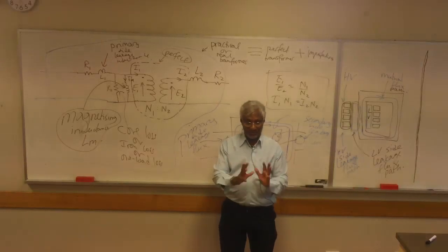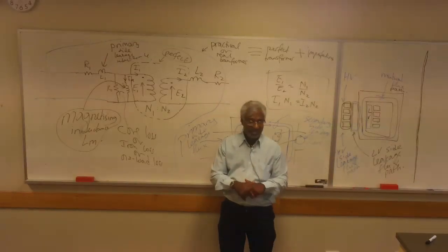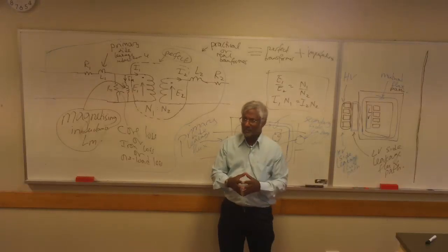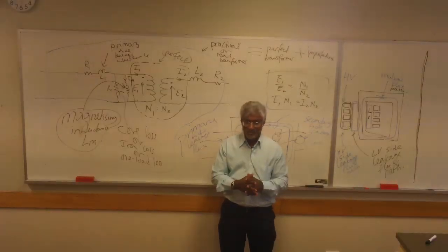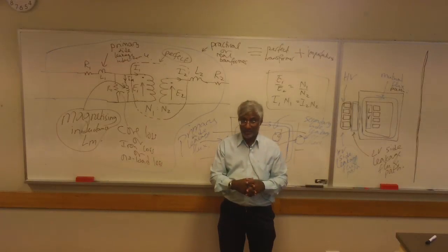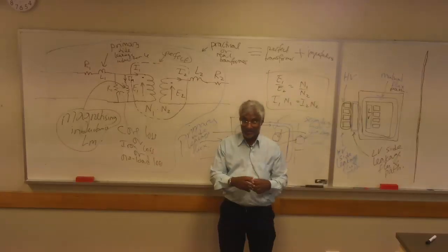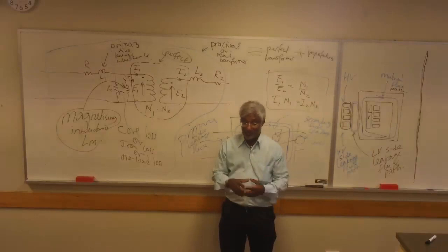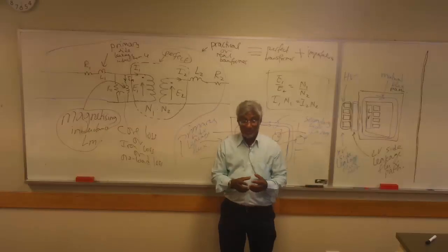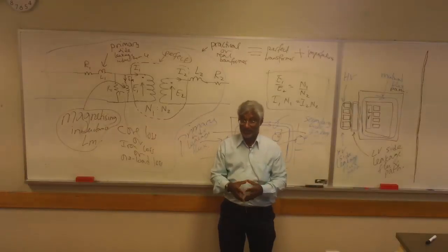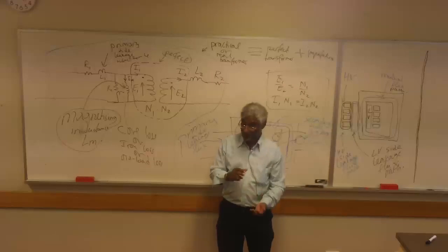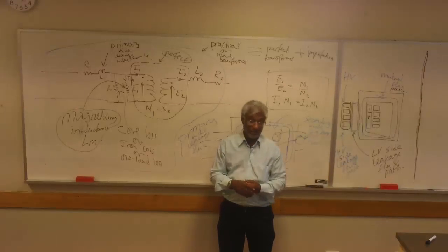You have to take all of these into consideration if you're looking at this transformer under high-frequency conditions, and one of those could be a lightning strike. With a lightning strike, the distribution of capacitance would decide where the maximum stress is on that transformer, because the stress is not uniform at high frequency.